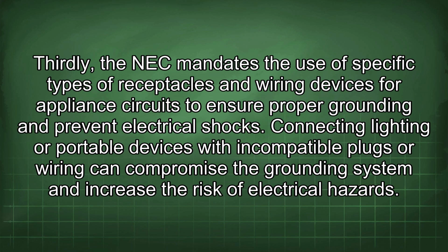Thirdly, the NEC mandates the use of specific types of receptacles and wiring devices for appliance circuits to ensure proper grounding and prevent electrical shocks. Connecting lighting or portable devices with incompatible plugs or wiring can compromise the grounding system and increase the risk of electrical hazards.